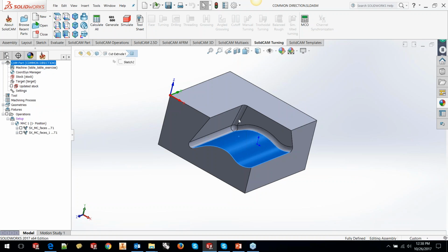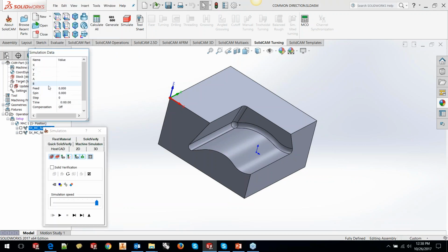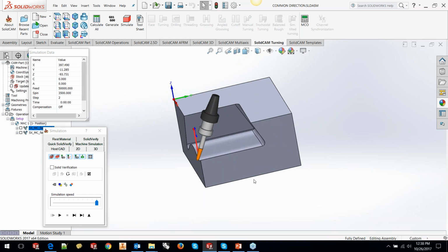And then I have a combination, which is a fillet, which has got both this angle as well as this angle. So the toolpath here looks something like this. If I just run the simulation, okay, because I have defined the tilt starting from a point, because I don't want to create a gouge check situation where within a short span of travel it tries to tilt. So I want it to tilt uniformly. So I've tilted it through a point. Okay. So what it basically does is, as it approaches that surface, because I've used a point, it's going to tilt itself and go into this area here.